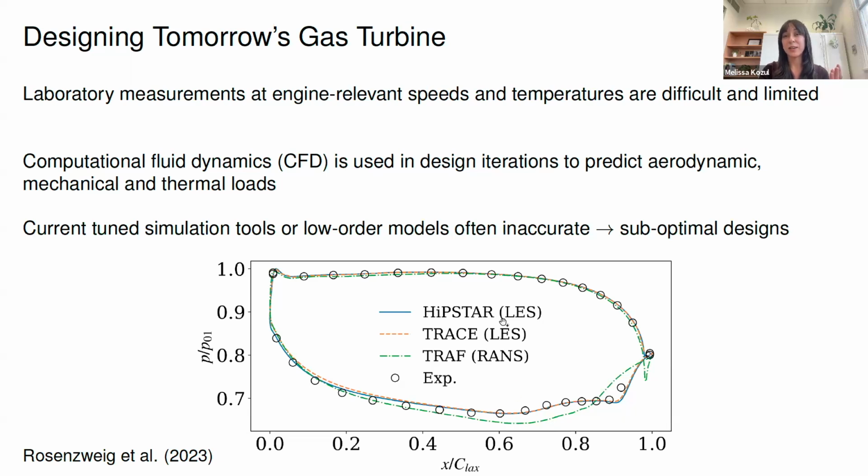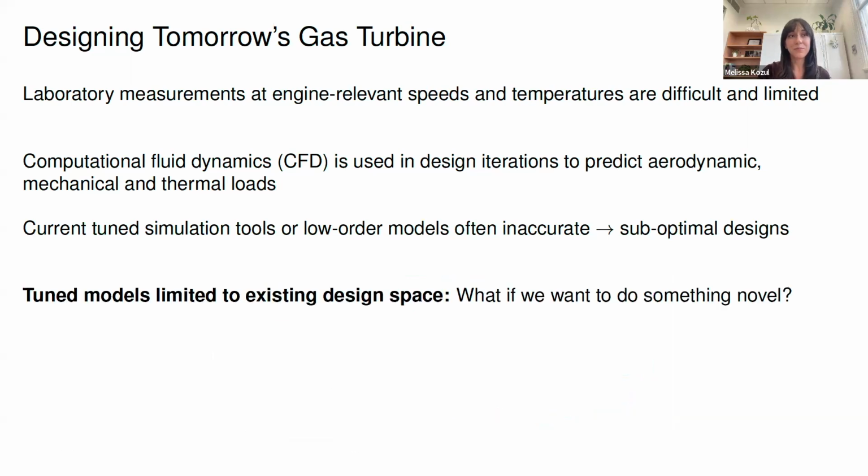Whereas this is a high fidelity method. HIPSTAR is our in-house code, whose development has been led by Professor Richard Sandberg at the University of Melbourne, and it really hits the experimental data very well. So we can predict these complex fluid flows that we saw on the previous slide very well with very good matching with experimental data. And then, of course, once we have this numerical test bed, we can then go on to do other things like, for example, put those riblets on, which I'll talk about shortly.